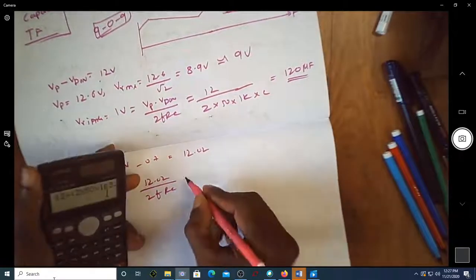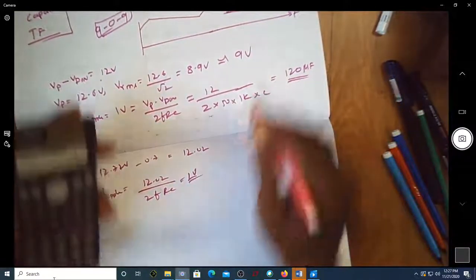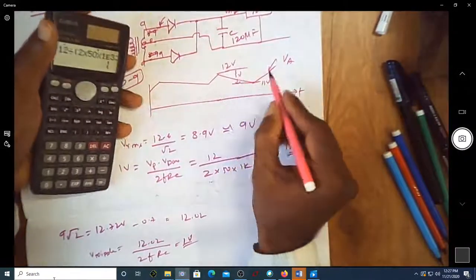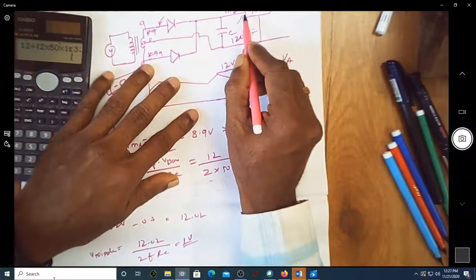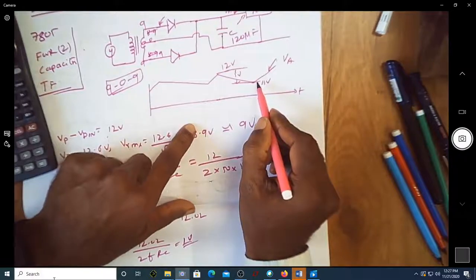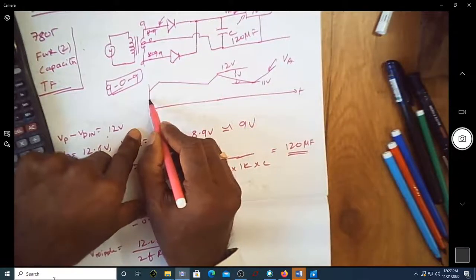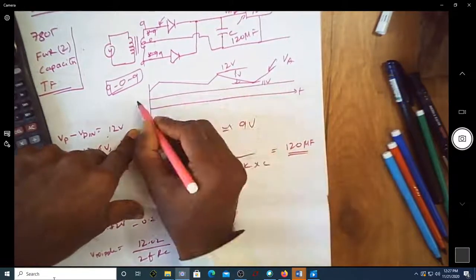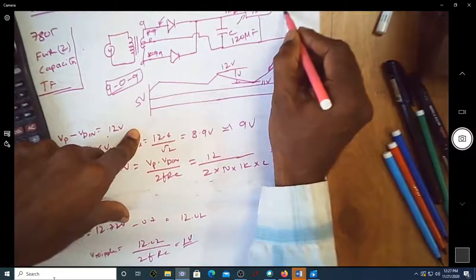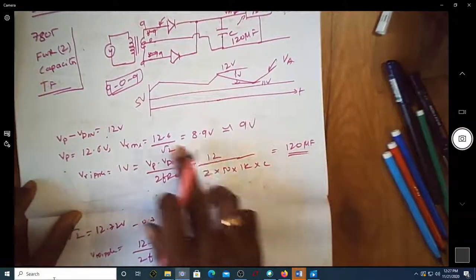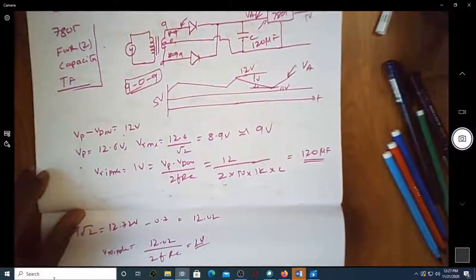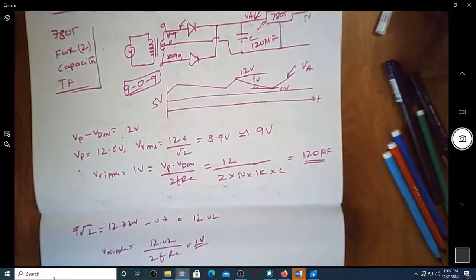You can see it's exactly 1 volt. So the input voltage to this regulator is always a minimum of 11, so you're bound to get a constant voltage of 5 volt at this point, because the input voltage is always more than 7, which is the minimum required. So you're going to get a constant 5 volt with this circuit.